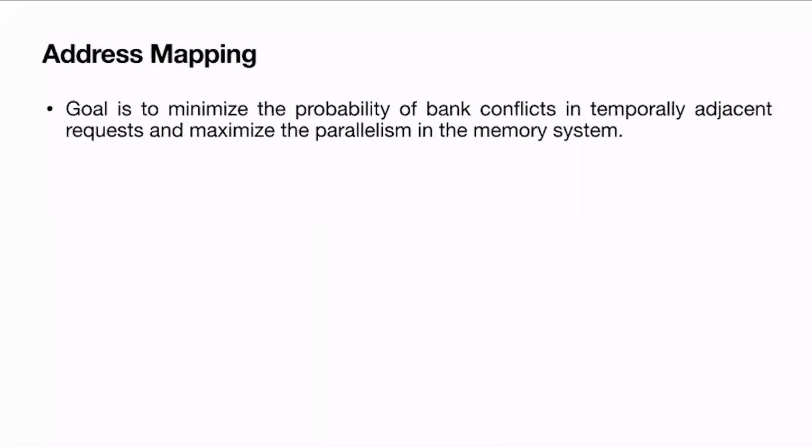Address mapping is another crucial component of the memory controller's functionality, which is going to say where the data is going to be placed. The objective of a good address mapping technique is to reduce the conflicts at the bank level. If you are going to keep accessing consecutive data, say you are reading data from 2 consecutive cache blocks, it is better to place these consecutive cache blocks into 2 different channels so that the 2 channels can work simultaneously, and you get 2 blocks of data in 1 unit of time, rather than placing them in the same bank, or in 2 different rows of the same bank.